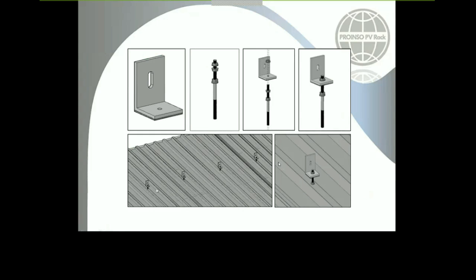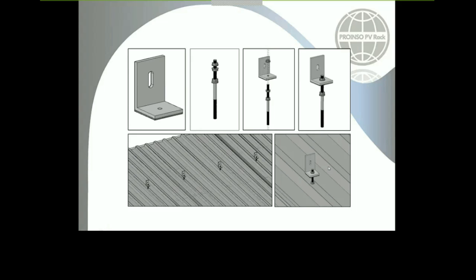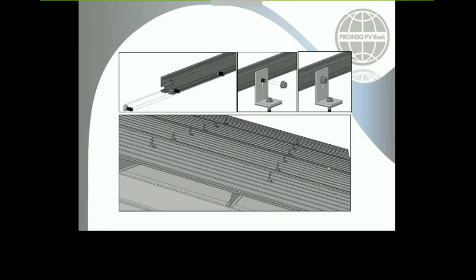When they are aligned and you have already placed where the fixings would be, you have to do some pre-drilling with a smaller diameter than the hanger bolt has, okay? You drill it, and then you have to screw your hanger bolt into it and fix the L connector on that. Just tightening it, you have the L connector. And the final solution has to look like what you could see here in the drawing, okay?